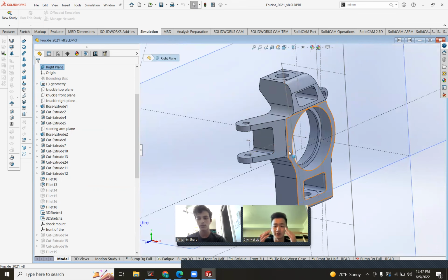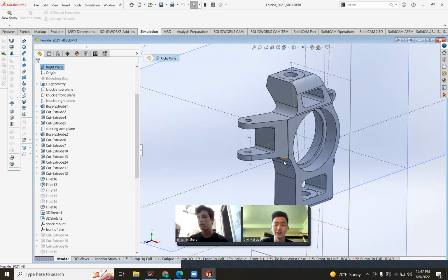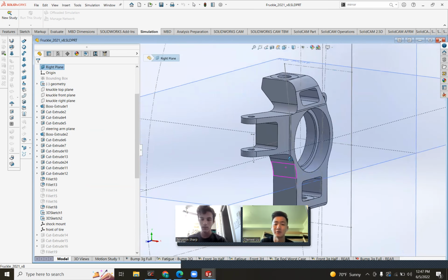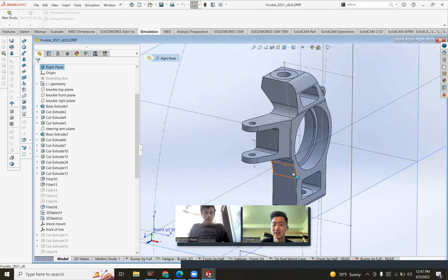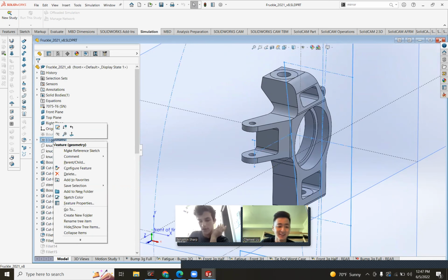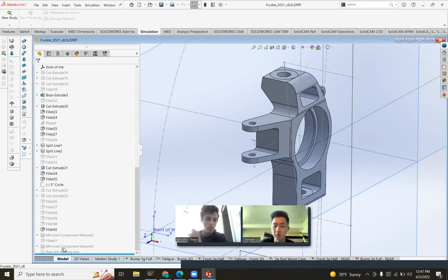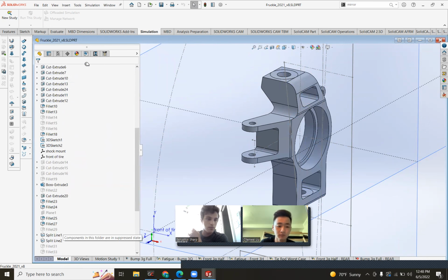For the knuckle, but when you're designing this knuckle, when you're cutting out material from the very first step, how would you determine how much to cut or what the geometry of the cut is? You just wing it? You have to wing it the first time and then you run FEA and you say, is this good? Okay, and then you change the geometry according to the FEA, right? Yeah.